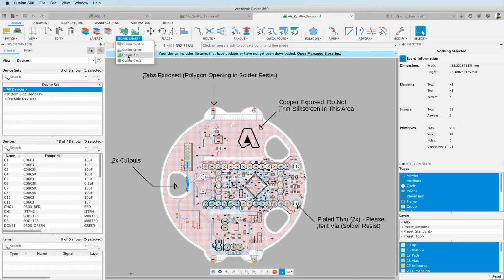Don't miss to use maybe a spline, you can use now. We have the move, all related to placing objects, and then we have the route options. That's the manual routing, and there are some in the menu bar here, but I can also click onto the drop down menu, and I have some options. Fan out. I have the quick route options you see here. There's also the auto router.